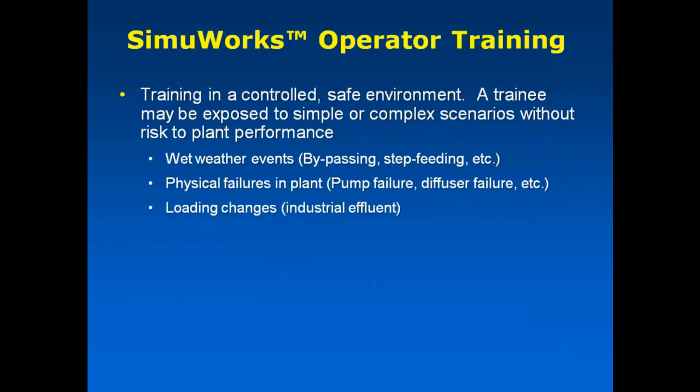This allows for training in a controlled environment. Different types of scenarios can be developed, such as wet weather events, where they're challenged with understanding how to bypass or step feed at their particular plant as appropriate. Possible operational failures of different parts of the plant, as well as loading changes. If you had a spill or some sudden change in loading, how would you respond to that?